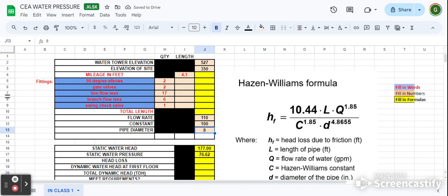That part was easy. Here's where it starts to get annoying. The effective length of the pipe, and that's that L. And it needs to be in feet. So let's do the easiest part first. Let's change that 4.1 miles into feet. So there's 5,280 feet in a mile, I mean. So we do equals I4. That's what this column is. I usually just click it.